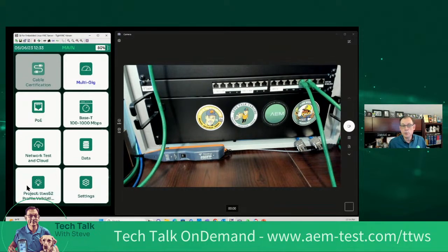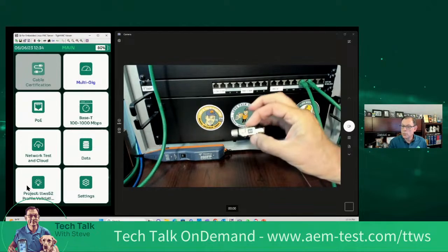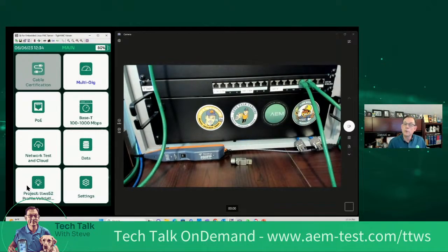And what I've showed you today is in our certification test, or the Test Pro, but all these functions are also available, with the exception of certification, in the NSA, the Network Service Assistant, and the Physical Cable Test and Network Service Assistant. It's not certification. It's what we call a Cert-A-Lite test. It's qualification plus. So it's using the same required test parameters: crosstalk, return loss, DC loop resistance. All those things are done on the NSA, just like they are on the Test Pro, but they're done from a single-ended perspective into a remote termination device like that. So it wouldn't qualify for certification, but it's going to give you most of that same information.